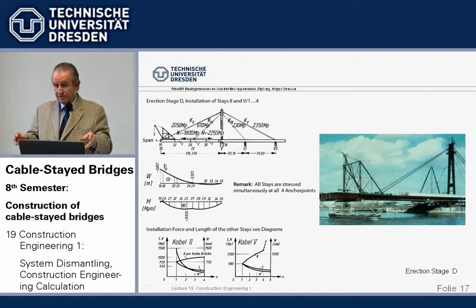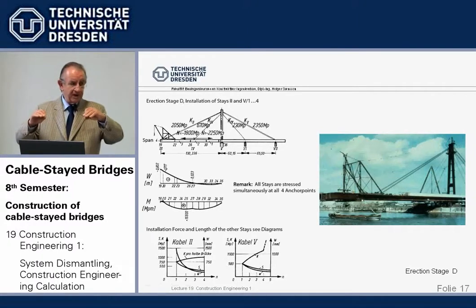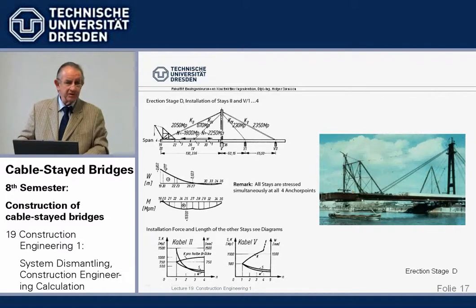If you want to lift simultaneous left and right, don't even try. Say you may either have the full difference, one up, one down, or so and so much is permitted, but never assume something happens simultaneous on site. Jack stressing left and right is the closest you may come to in real life.